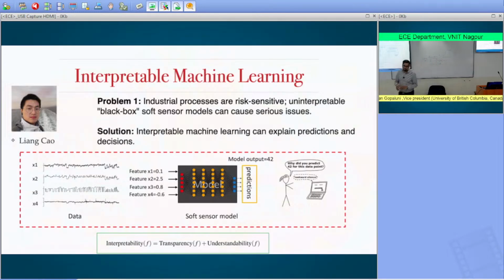A clamp on a variable means you put a constraint on the variable, and you say, don't increase this variable. They changed that in the MPC code. They finished their repairs, and they forgot to remove that clamp in the model predictive controller. It's an optimizer. It's just trying to find the optimal solution to whatever conditions it is facing, right? And that was not good.